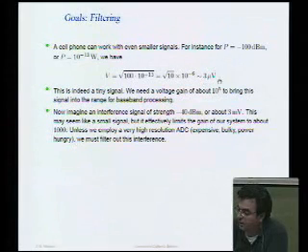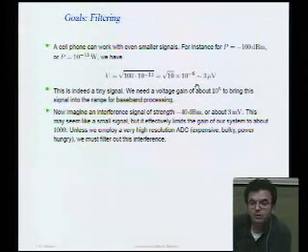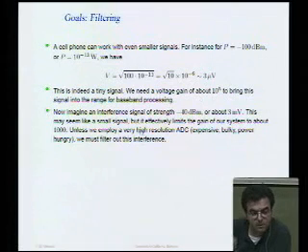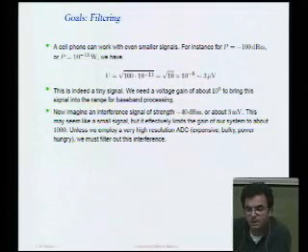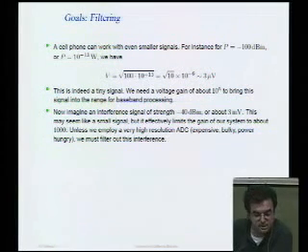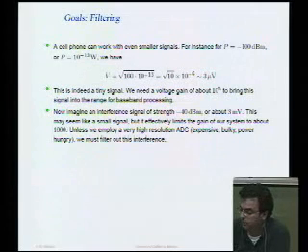In order to take 3 microvolts, let's say, up to 300 millivolts, in order to digitize it, we need a gain of 10 to the 5. So if we can't get rid of this interference somehow, we can only have a gain of 1,000, which means we're going to have to either give up on communicating when we have interferers, or we need an extremely sensitive analog to digital converter, which is going to cost us a lot of money and a lot of power. Therefore, it's not going to be portable.